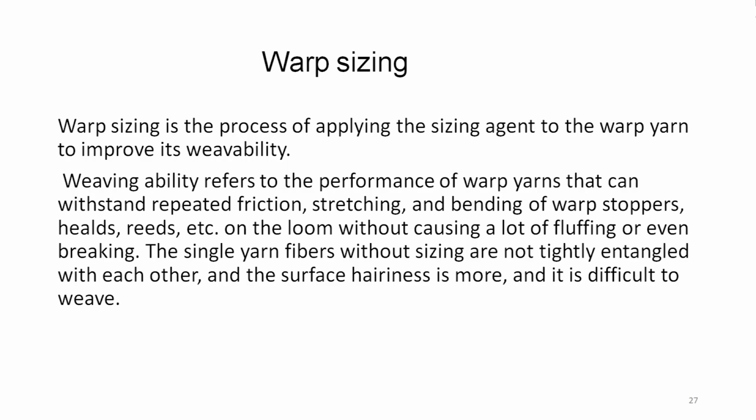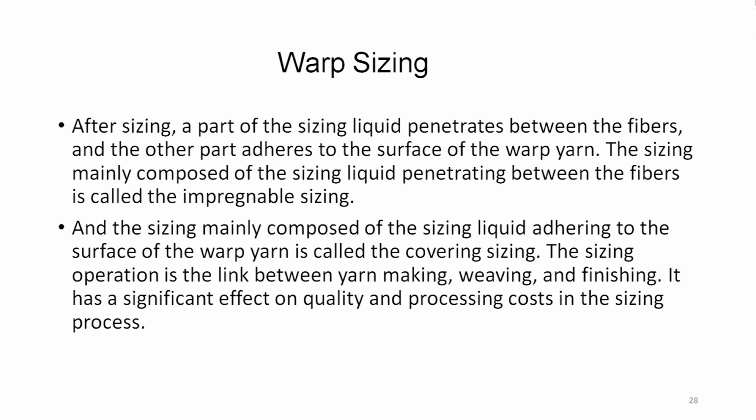The single yarn fibers without sizing are not tightly entangled with each other, and the surface hairiness is more, and therefore it becomes difficult to weave. Therefore, sizing is necessary and warp sizing is equally necessary.